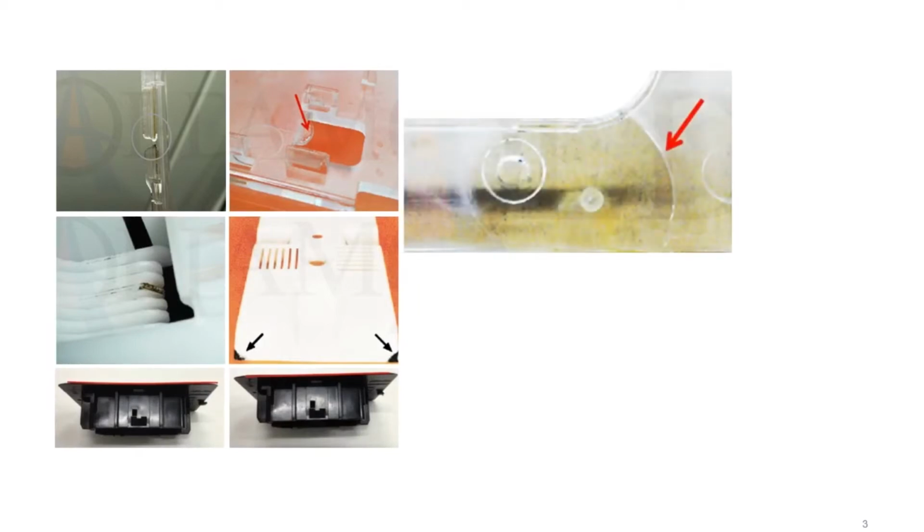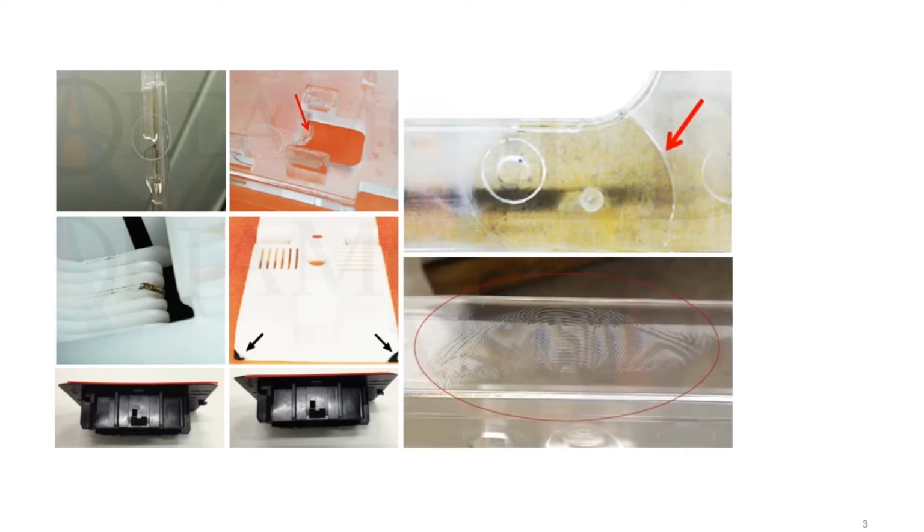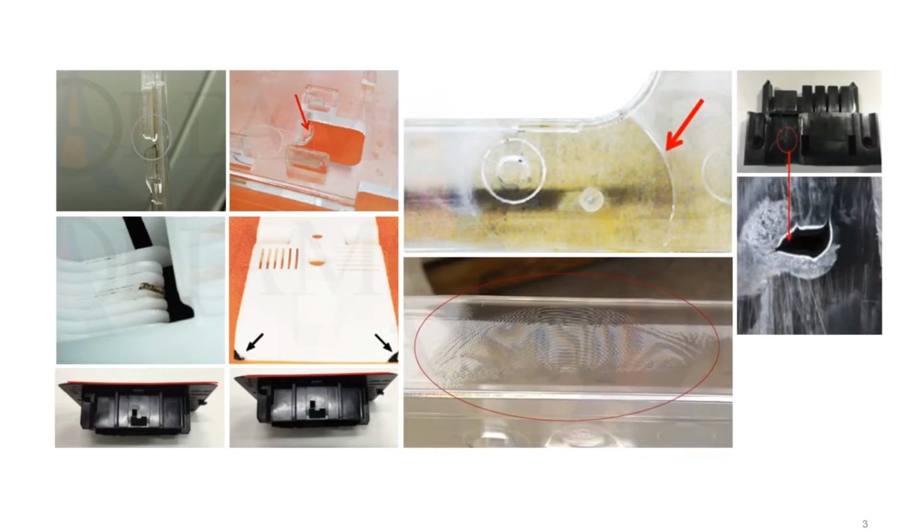For example, short shot usually happens at the filling end, where somewhere the plastic is too thin. Plastic melt goes out from the cavity to form flash. Burn mark usually happens at the filling end as well. Warpage results in a non-flat part. Weld line makes a bad appearance or structural weakness. Air trap and stress mark also result in an NG part with bad appearance.